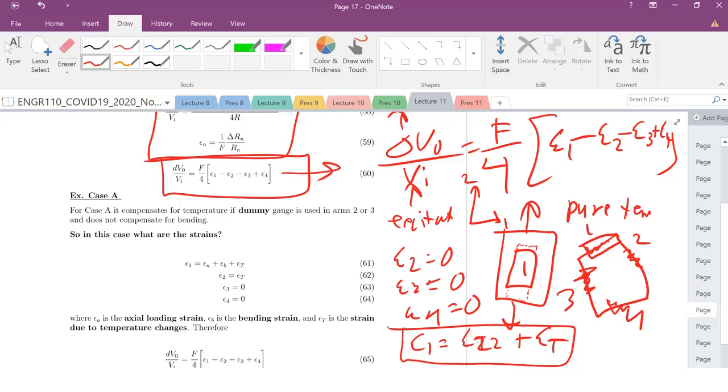And that's it. So again, if our wires are going in this direction, that will be our value here. Now what happens if we're elongating that strain gauge? If we're elongating our wires, that is going to be positive. If we're compressing our wires, that is going to be a negative value. So we're going to have to work with that in just a second.